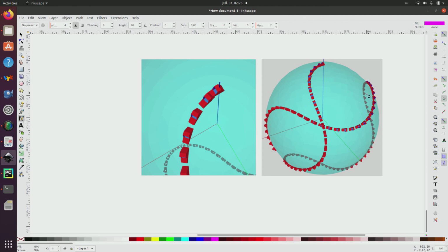My trajectory is represented here, and on the left I have a zoom, with the initial position R0, which contains the position but also the heading. We can see that I have an acceleration due to the overlapping here. The orientation at the beginning is R0 equal to identity, and I see that I am aligned with the axis. Okay. The trajectory on the sphere corresponds to one trajectory in SO3. Recall that I have to add r to have a representation of the state space. In the trajectory here, I have one loop, which shows the importance of SLAM techniques to detect loops.